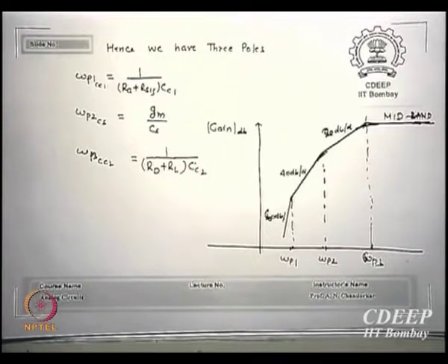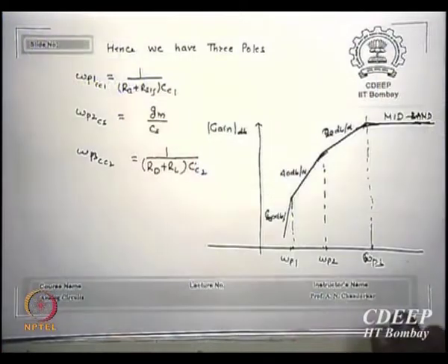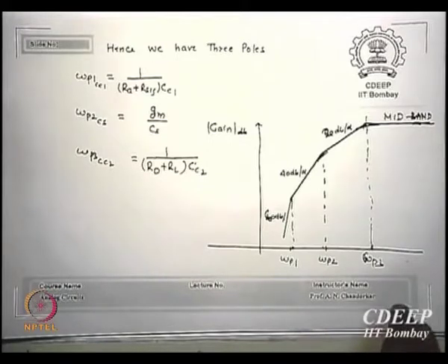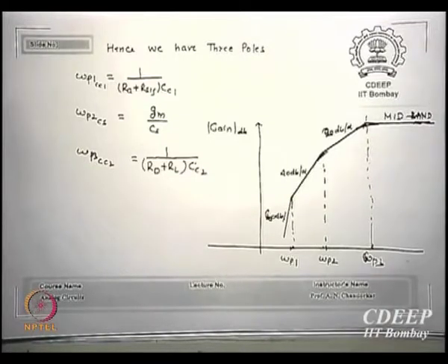Essentially what we are saying is that once you rise, the second pole spills over and gives another 20 dB. Because it's a pole, it must decrease. A pole means it will decrease. 60 becomes 40, 40 becomes 20. Is that clear? Each pole gives minus 20 dB, so it went from 60, then came down 20 to 40, then 20 more to 20. Is that okay? And then it reaches, so what is FL here? Which value is FL? Omega P3 is 1 upon 2 pi, FL is omega P3. So I got my lowest cutoff frequency which I can evaluate and say, this is the FL.